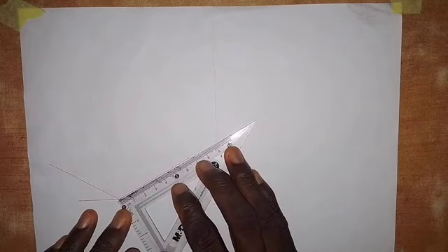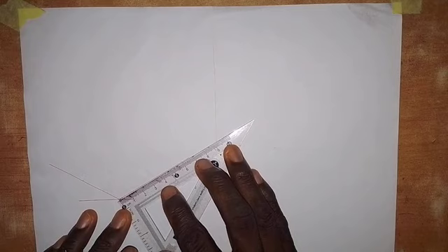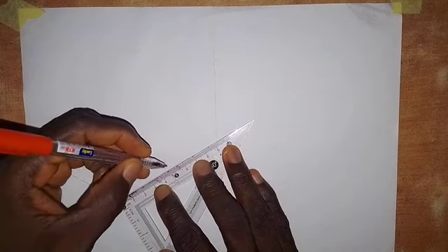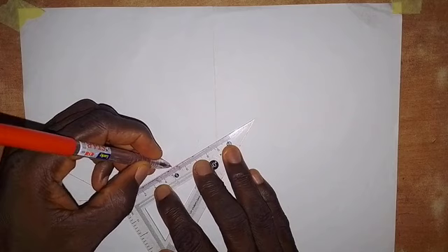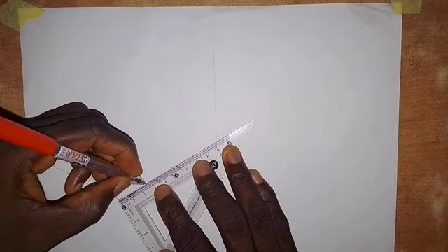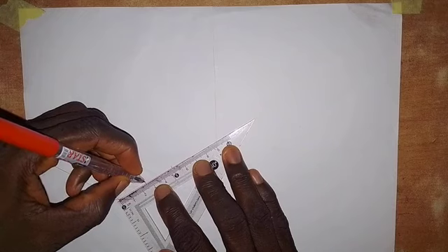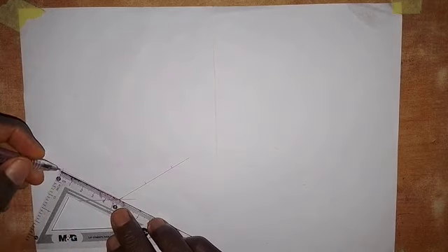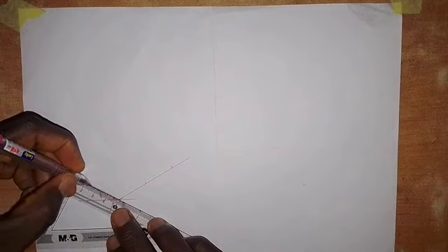Now, let's say the length of the diameter of the circle is 50 millimeters. Diameter of the circle that we have to construct, isometric circle that we have to construct, is 50 millimeters. So from this point now, where these two lines intersect, take a measurement of 50 millimeters, okay, and get the midpoint of this line, which is 25 millimeters, okay. Then you come to this point and take a measurement of 50 millimeters from this point here. So this is 50 millimeters here, and get the midpoint, which is 25 millimeters from the point.